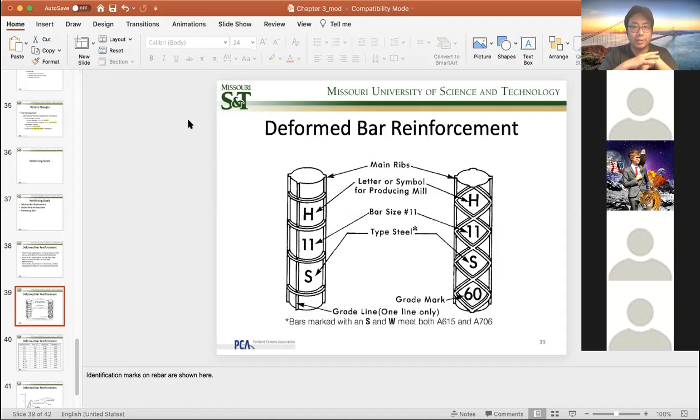The reason is cost, right? Unless we have different molding, we can actually fabricate different rib geometries to achieve the ultimate purpose, like you were saying, Dalton. Unfortunately, the industry is a pretty standard industry, okay? So what happened is, back then, right after the Second World War, the United States tested thousands of bars from the manufacturer point of view, okay? And they found a specific geometry and ratio that gives you the highest bonding strength between the bar and concrete, and called it good, okay?